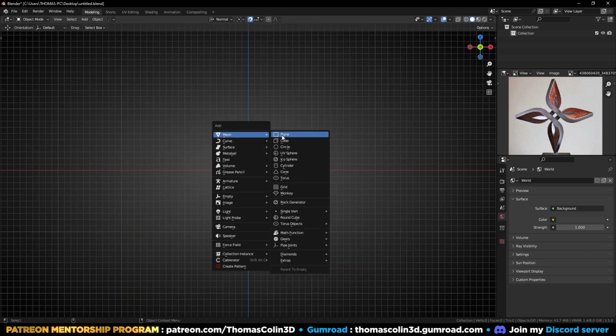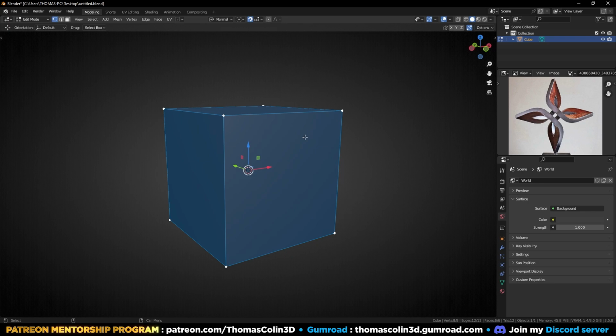So first, let's add a cube. In edit mode, remove everything but the vertices. So click on only edges and faces. And now we have to connect the diagonals. So like this, like this, like this, connect, connect, connect. And now we have to fill the faces. Like this and like this, okay? So we can select one vertex, press Shift G and select amount of connecting edges, and you can remove them.